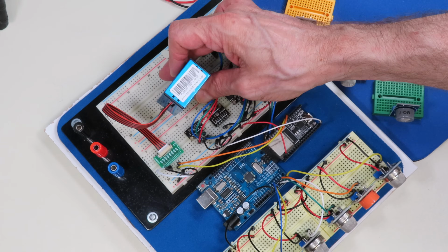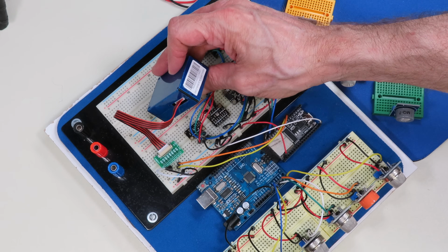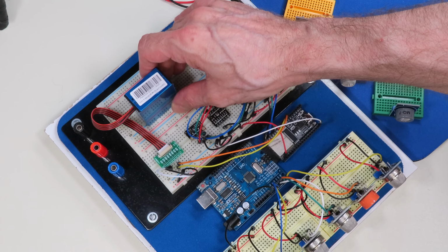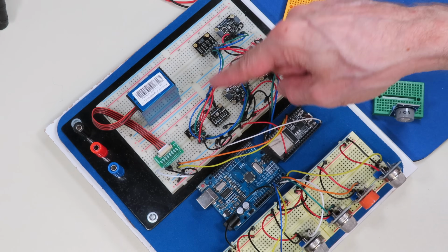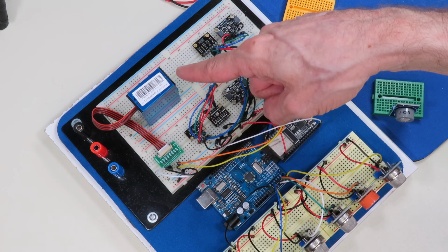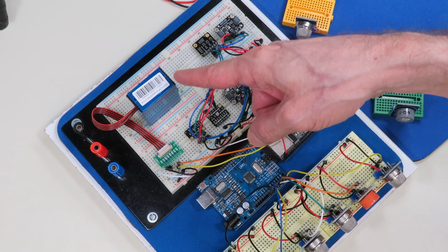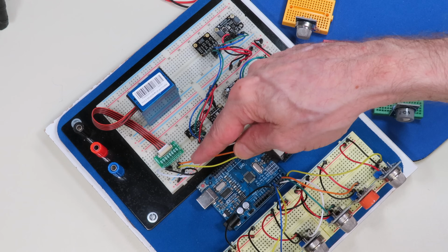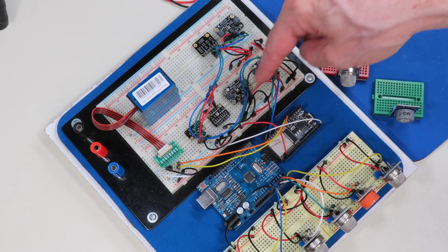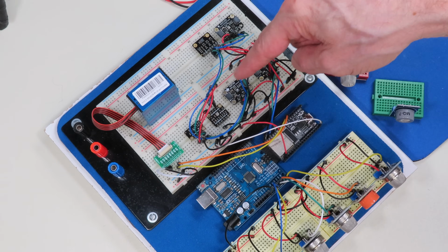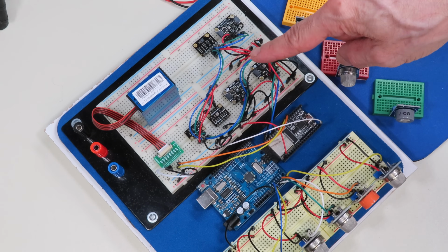This tiny little box is actually a sensor. It's what's called a particulate matter sensor. It senses little particles inside the air, and this is a PM2.5 particulate matter sensor, which is a pretty standard device, and it has a serial output, so it's going to one of the UARTs on the ESP32. The rest of these are all I2C based sensors, and I'll tell you what they are as follows.